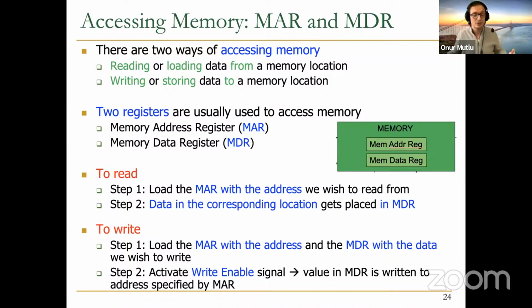Timing is important so that you know exactly when the data will appear in the memory data register. Assuming that a memory takes one clock cycle, you need to ensure that you wait enough combinational delay, as we discussed, plus the delay of the latches. If you remember the setup time and the hold time of the timing, you need to ensure you wait enough